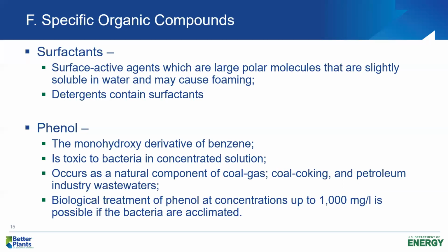I've seen municipal plants that received a few milligrams per liter of alkyl phenol ethoxylate surfactants actually wipe out the nitrification in the process, which may be a very disruptive impact on the treatment plant, especially if we have to meet an ammonia or total nitrogen limit in the effluent permit.